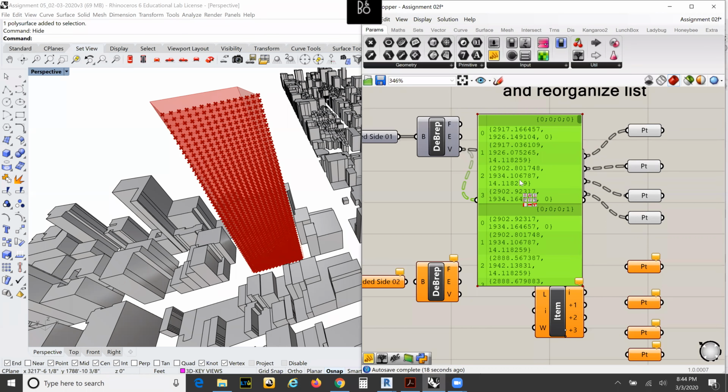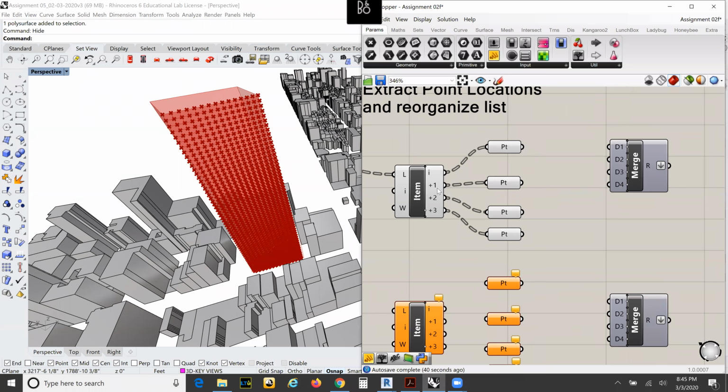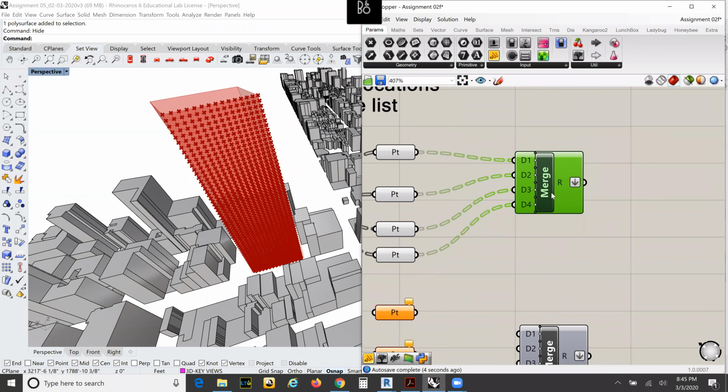Like I said, when Revit reads things, it sometimes reads them a little differently. So we're deconstructing it and reconstructing it in this exact order. It might already be in the correct order, but your mass might have been generated a little differently than mine. So we're going to break it up, and then merge all these pieces back together again. You don't really need a fifth one.